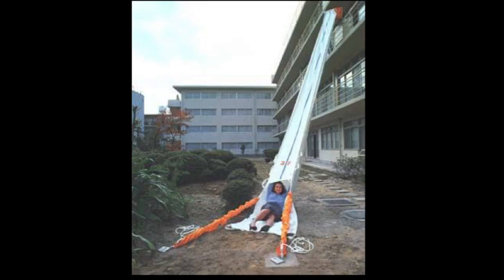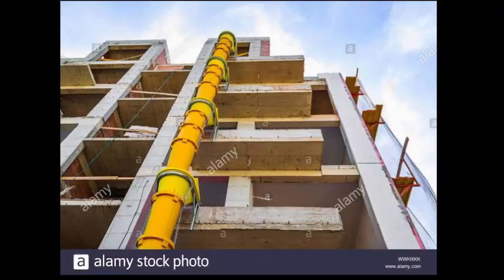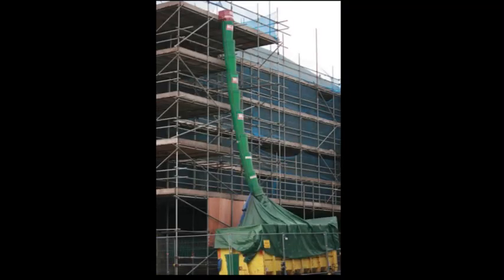Construction chutes are used to remove rubble and similar demolition materials safely from taller buildings. These temporary structures typically consist of a chain of cylindrical or conical plastic tubes, each fitted into the top of the one below and tied together, usually with chains. Together they form a long flexible tube, which is hung down the side of the building. The lower end of this tube is placed over a skip or other receptacle, and waste materials are dropped into the top. Heavy-duty steel chutes may also be used when the debris being deposited is heavy-duty and in cases of particularly high buildings.